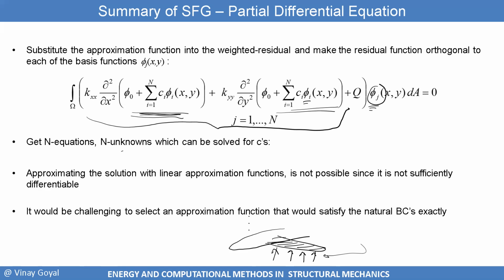I want to come up with a method that can easily be implemented, and that maybe all I have to do for the finite element then is to just specify the fixed conditions, and I have to make sure my approximation function satisfies the essential boundary condition only.